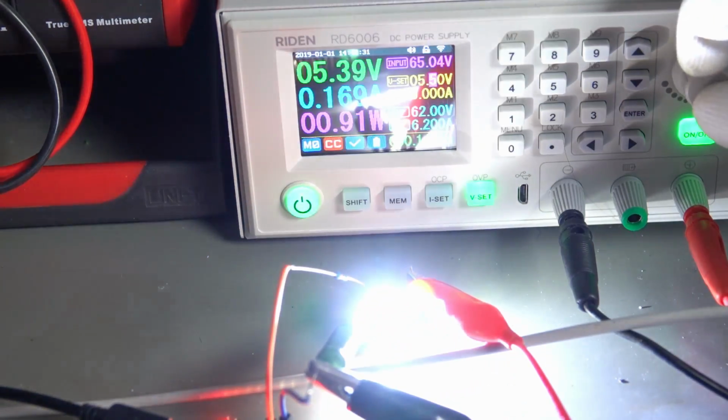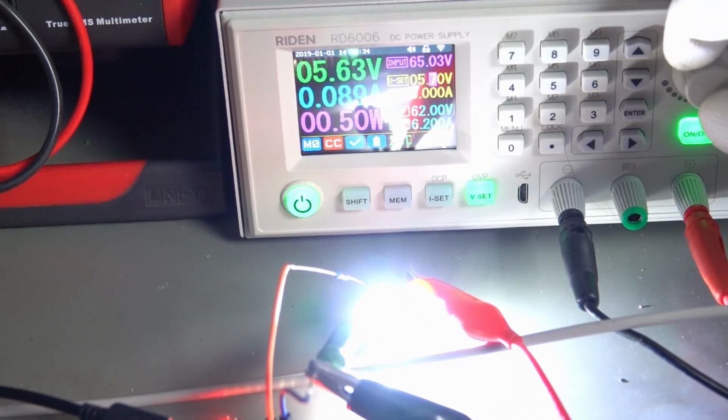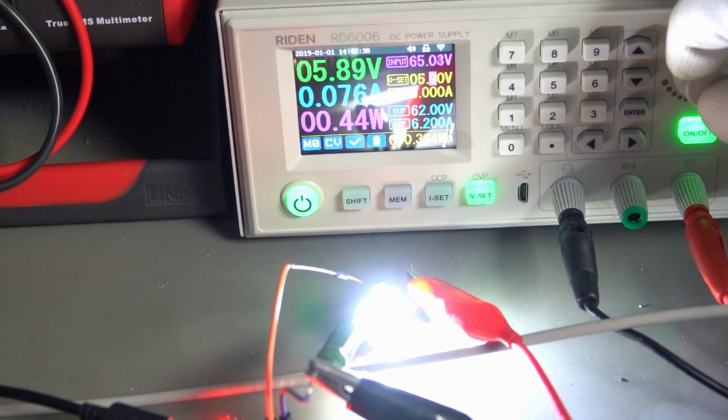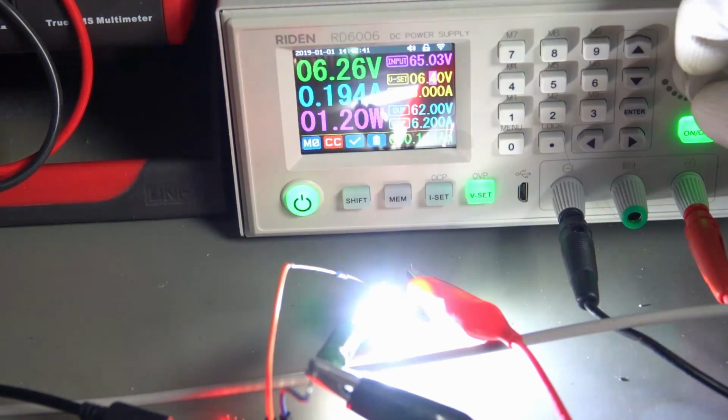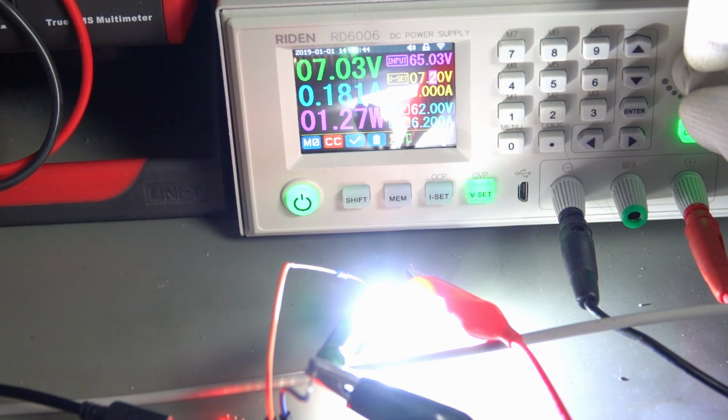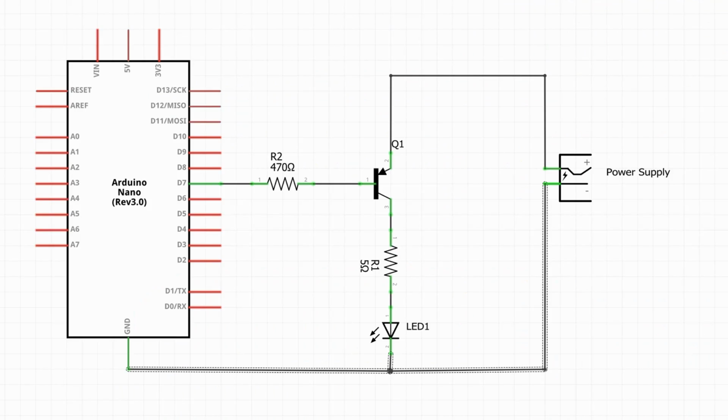Strange, the LED does no more switch completely off. And now it stays always on. Not good. Did we already create the first casualties? No, it's quite easy. High on the Arduino is 5 volts. And if we go higher than around 6 volt, the transistor stays on whether the pin is low or high, because it has a negative base emitter voltage all the time. This is what we have to keep in mind if we want to use transistors on the so-called high side.